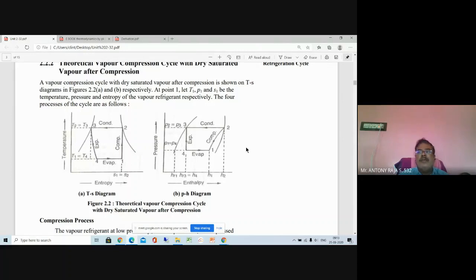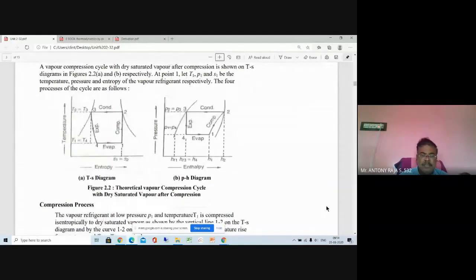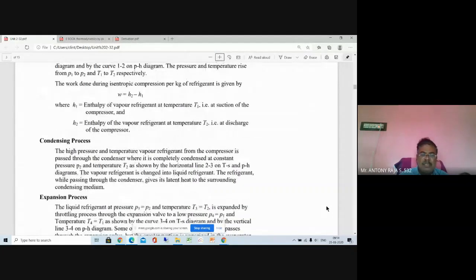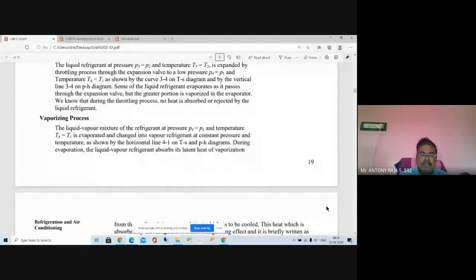So if you reduce the power consumed by the compressor motor, then you can improve the COP. These are the two ways. Also, if you reduce heat loss from the system, refrigerant leakage, or friction losses, you can improve the efficiency. We know the COP formula, which you already studied in the laboratory class.